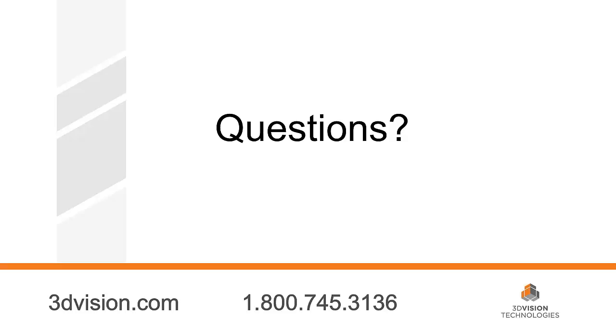We've got time for one more question, then we're going to have to end. So why don't you take this last one? Yeah, it says, does saving a subassembly as a part file help performance? I would say yes and no. Majority of people, I would say yes, because you're taking a subassembly that might have mates to it and changing it into one rigid body. Typically when you have a subassembly, it's already a rigid body, so it's barely worse than a part file on its own. But yeah, that could definitely be a helpful thing.